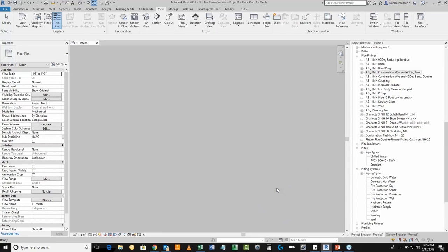So here in Revit we are looking at the pipe fittings, the pipe types themselves, as well as the system types. Now we're not going to get so much into system types today because we're setting up routing preferences, and routing preferences live at your pipe types level. However, your routing preferences obviously require fittings in order to be set up, and so your fittings need to be loaded into the project. If you forget to load your fittings into the project before you get into setting up your routing preferences, as you'll see here shortly, there is a nice little load families button inside of routing preferences so that if something you want isn't there, you can load it without getting out entirely of the routing preferences.